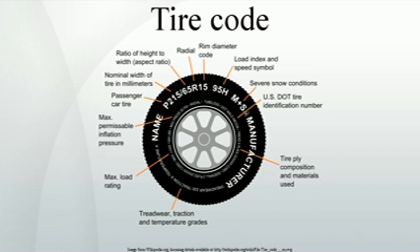The diameters referred to above are the theoretical diameter of the tire. The actual diameter of a specific tire size can only be found in the TRA yearbook or the manufacturer's data books. Note that the tire's cross-section and diameter are always specified when measured on a wheel of a specified width. Different widths will yield different tire dimensions.